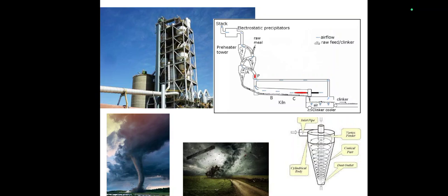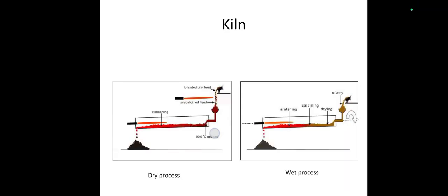Under the rotation of this hot air, the two different materials will mix uniformly and almost get dried up, and the temperature shoots up in this dry heater. Then once it enters the kiln, with less time and less effort the fusion can occur. So this is the main beauty of the dry process.